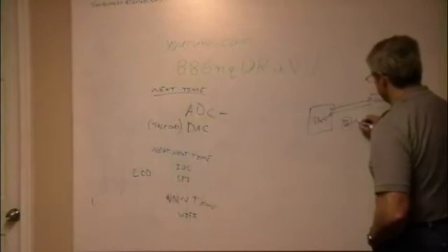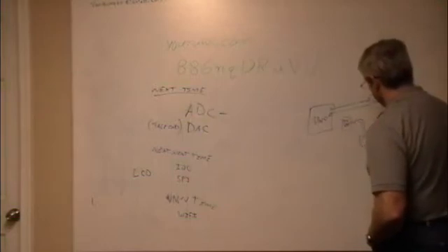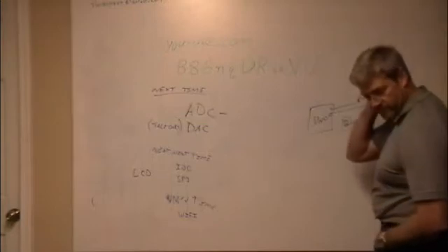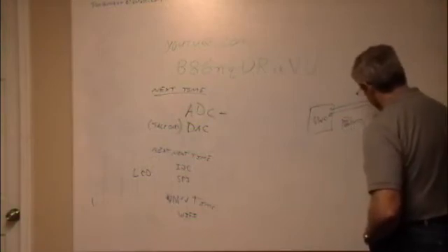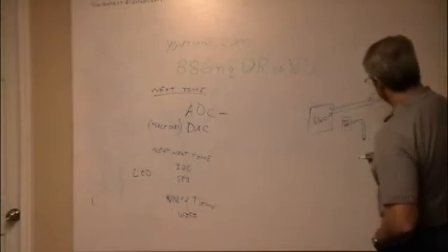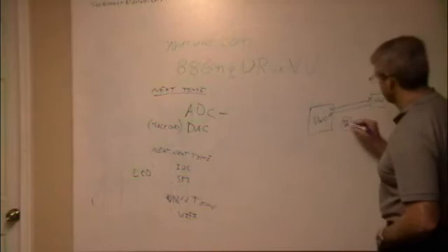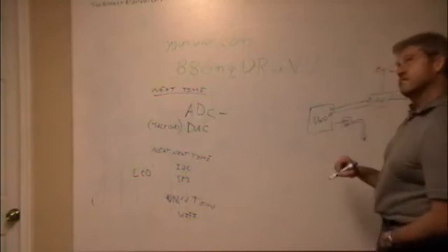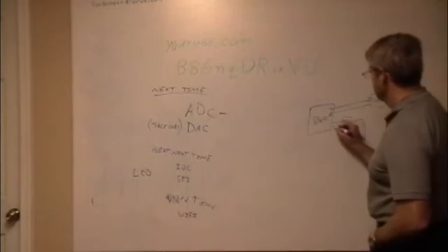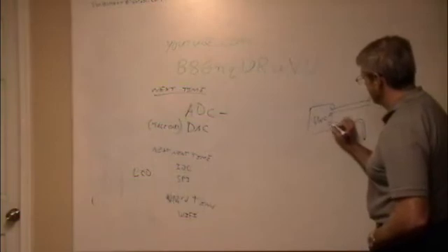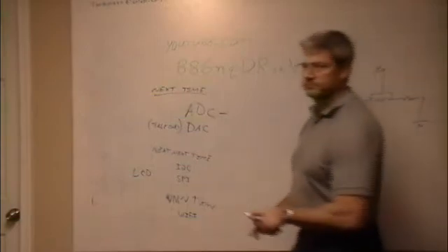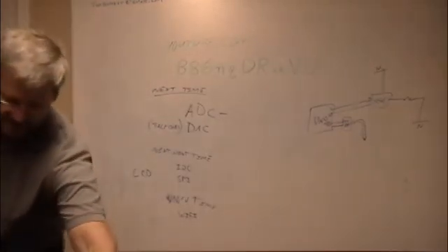which has 2 wires that go to the thermocouple. I don't remember what the symbol for a thermocouple is. Oh, I do. A thermocouple, the symbol is this. And that's inside your oven. And then that comes back, 2 wires, or maybe 3 that are powered. And one of these will be, this is the symbol for an analog to digital converter, which is built inside of there. There's a 10-bit ADC in there, and you'll only need 8 probably.